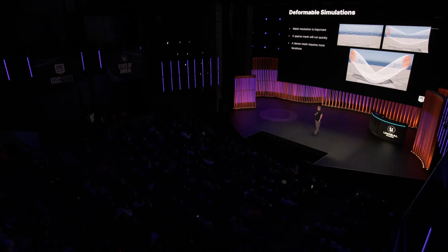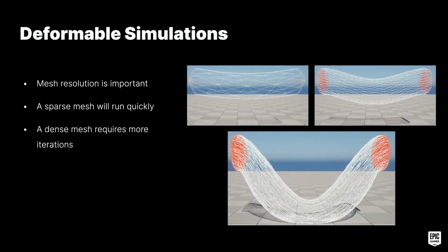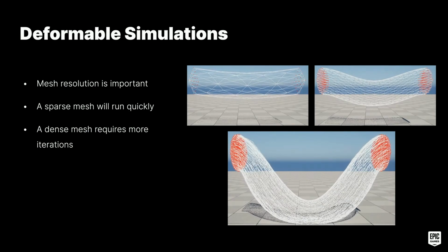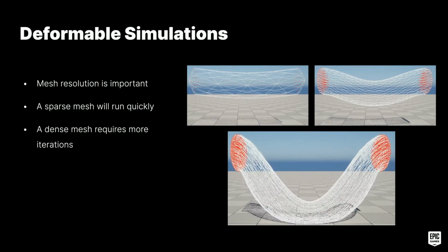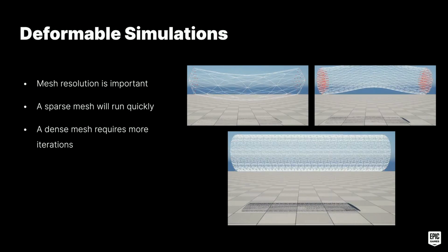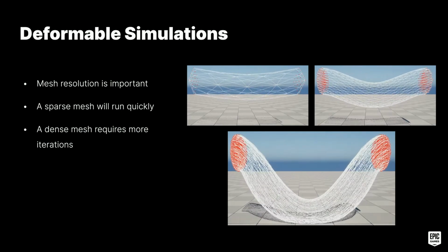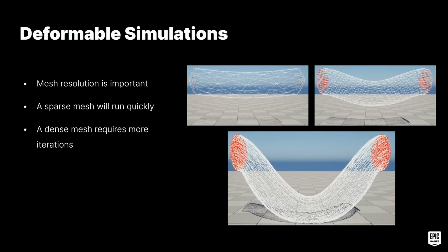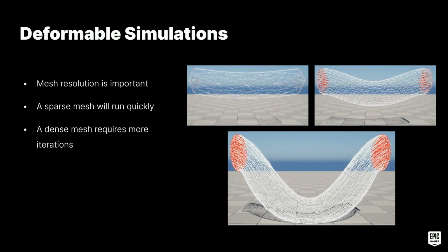For the Rivian simulation, we were targeting speed. The results needed to run on a reasonably high-end PC and remain stable and artifact-free, which can be quite a challenge for dynamics across volumetric meshes. For example, the density of the mesh, or just the number of connections across the mesh, can dictate the iteration requirements of the solver. As a result, a denser mesh will require higher iteration counts to properly propagate the energy through the system. Therefore, a balance needs to be found that allows the mesh to remain visibly plausible but performant and within budget.